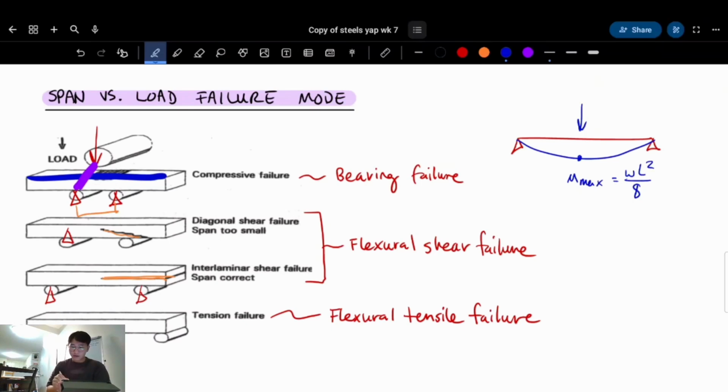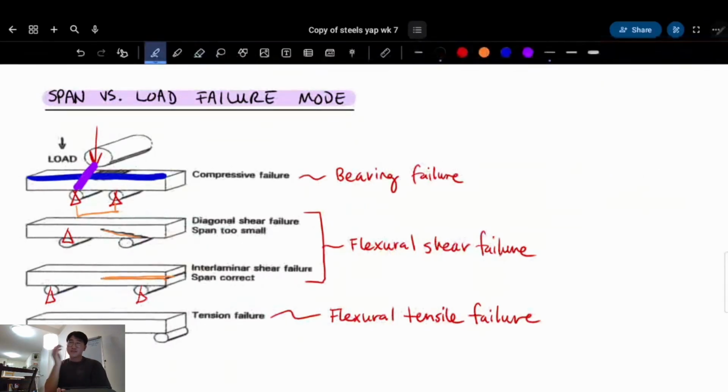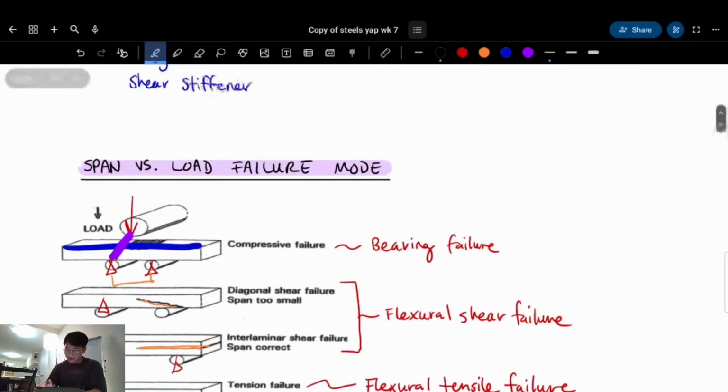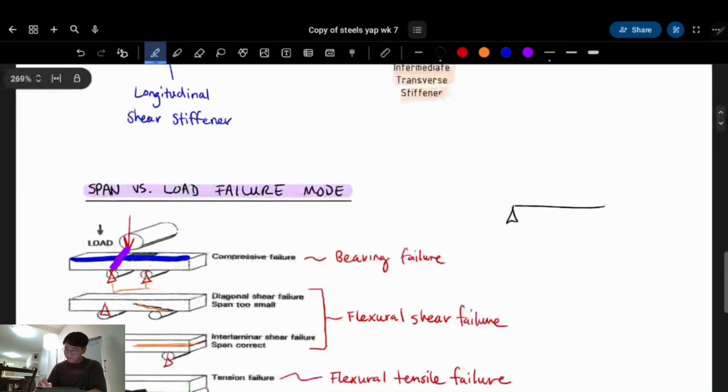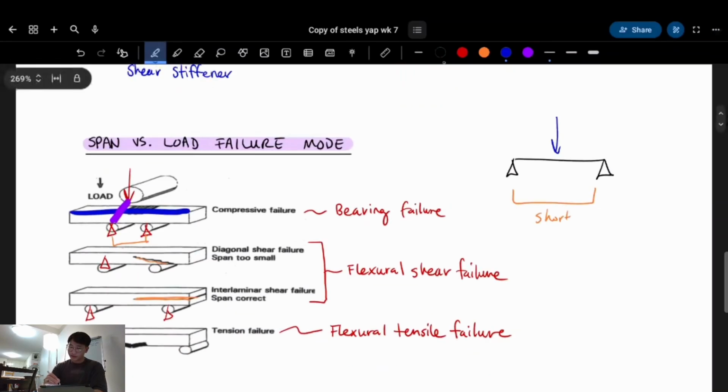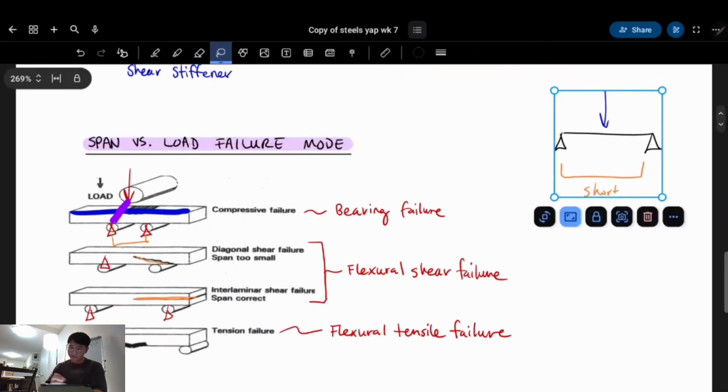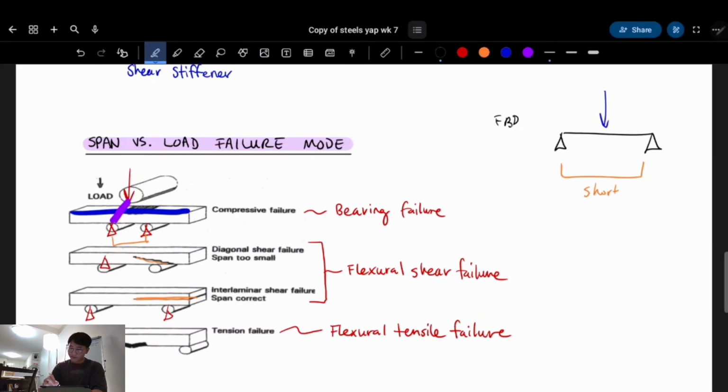Yeah, so a simple way to understand whether shear will govern your beam or flexure will govern your beam is basically, if your beam has a fairly short span and it has point loads, right? That's where shear is dangerous, because if you think about the diagram for this, so this is your free body diagram, and if you think of the shear force diagram, your shear force diagram will look something like this, right?